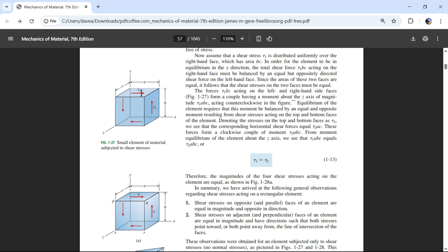And similarly, if I have a stress in this direction, it's proportional to the force in that direction. The force will also be in that direction. Therefore, the stress over here has to also be downward. So even though this isn't a free body diagram, in the stress diagram, if this is upward, that has to be downward, and they have to match based on the surface areas. The surface areas are equal, therefore this stress down has to equal that stress up.